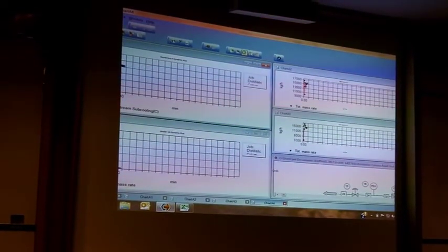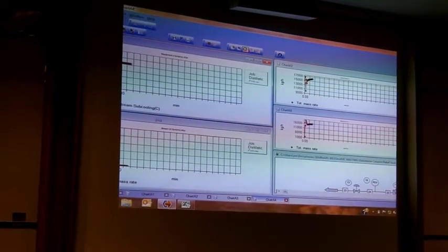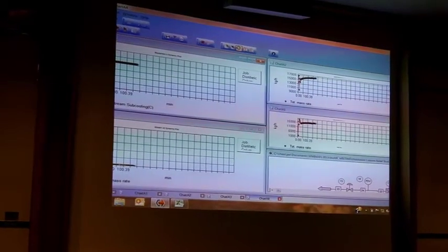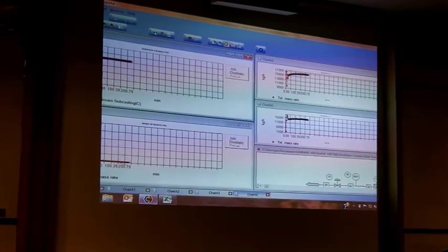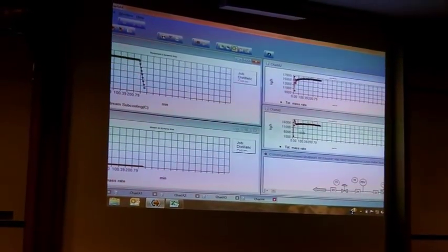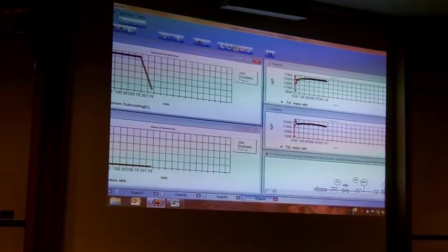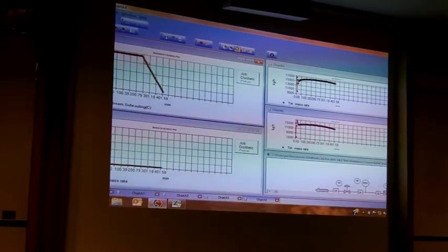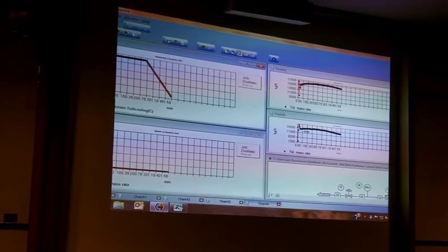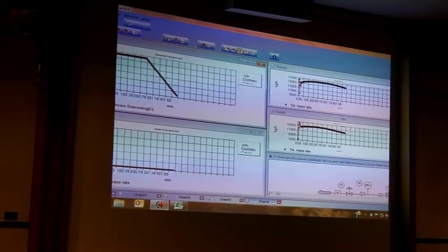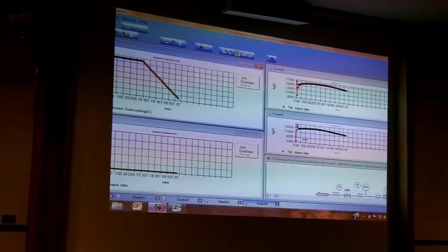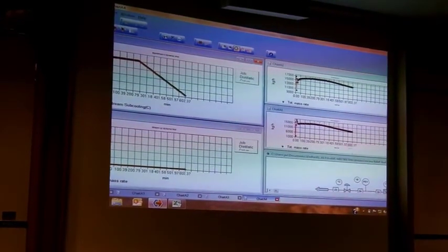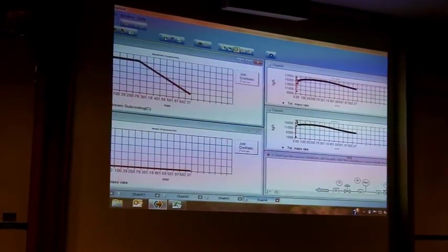So off we go. This is the subcooling on heat exchangers. This is the relief line here. This is the vapor load from the top of the column. There's the heat exchanger, the condenser's fouling here. This is the reflux flow. That's the overhead flow. When you start to see these dropping, that's when the pressure ramps start to come in.